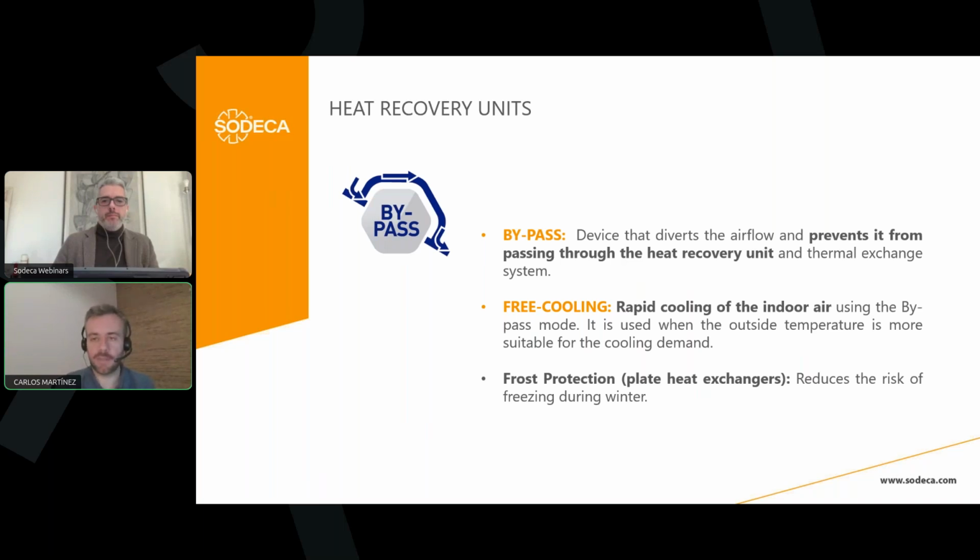So if the temperature sensor detects that the temperature outside, for example, in summertime, is lower than inside, it could be interesting for us, instead of using the air conditioning system, to use the bypass mode and to have a free cooling of the indoor air. Okay, so that's why the bypass is so important, and it's going to be a key factor in the energy efficiency of this equipment.